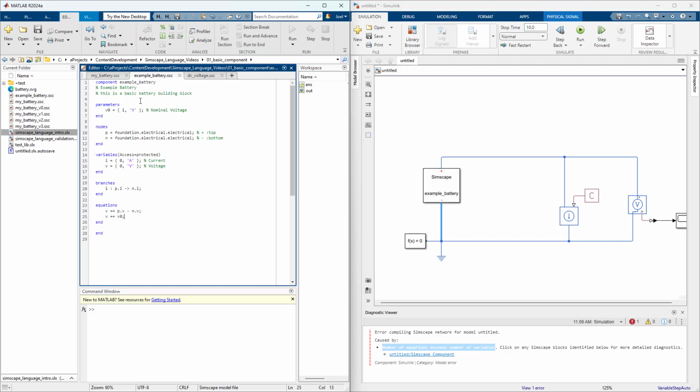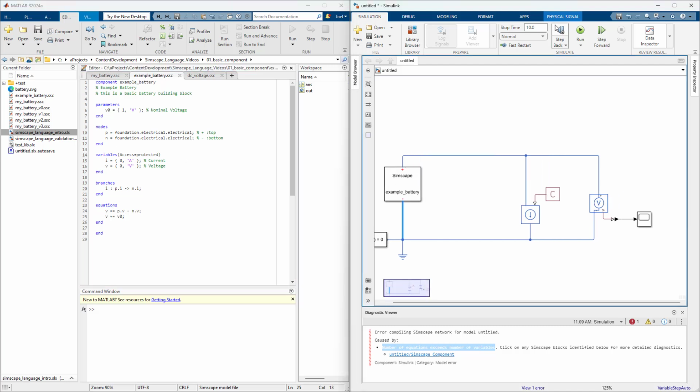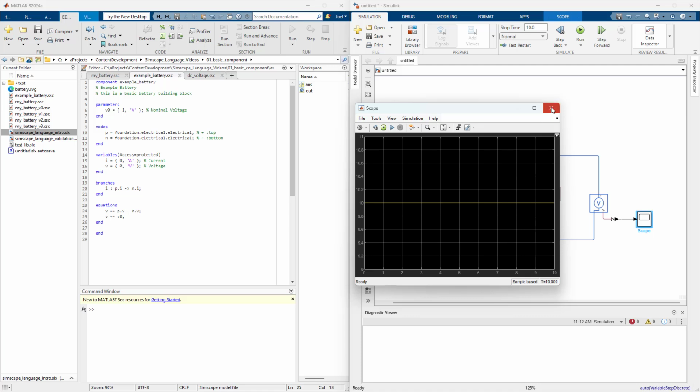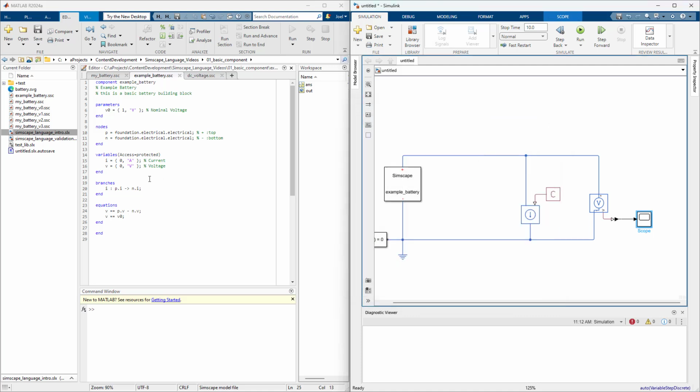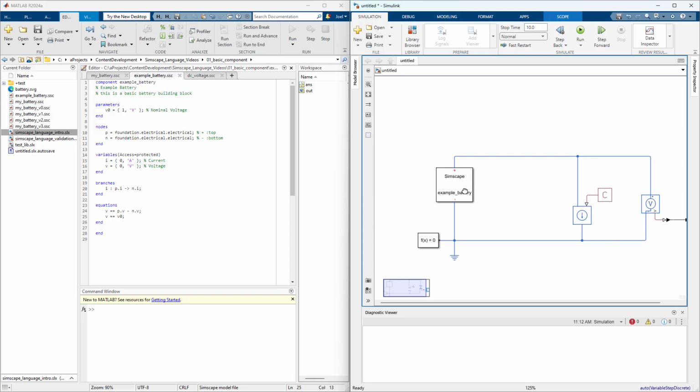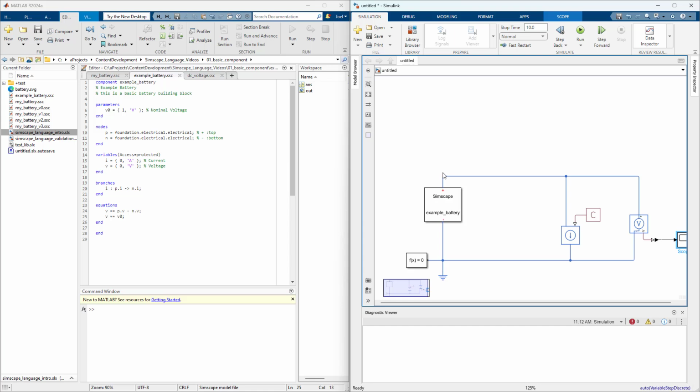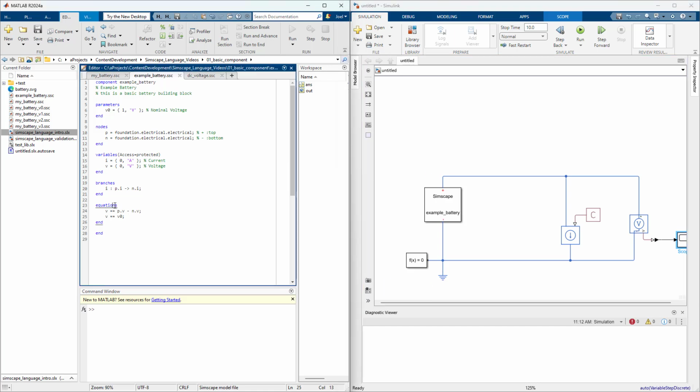So we now have this really basic block that we can start building off of. So we've accomplished the first goal. We have a constant voltage source, which we have gotten predominantly just by stealing and tweaking existing code. And we are going to continue that approach when we add resistance. So I want to add resistance to this block, and I could actually add equations. So I could add a parameter here for resistance, and I should actually do that.